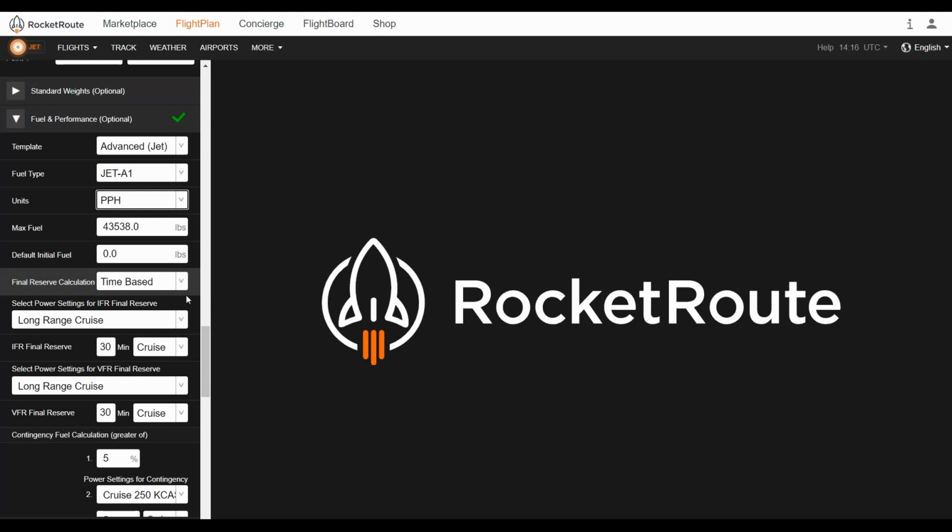There are two options to calculate a final reserve in our system. It's either time-based or constant. I will start with time-based at this point. For the time-based calculation, you can define which cruise profile will be used, the time, and also the altitude. It's either cruise altitude or 1500 feet.